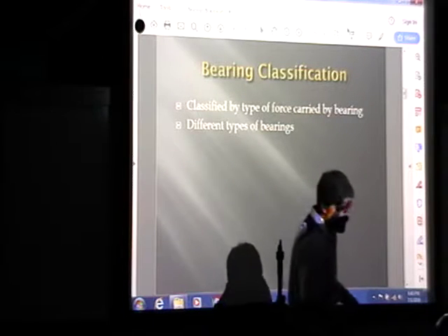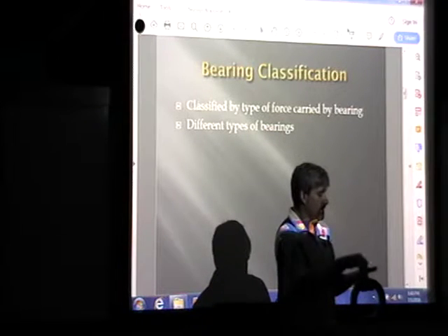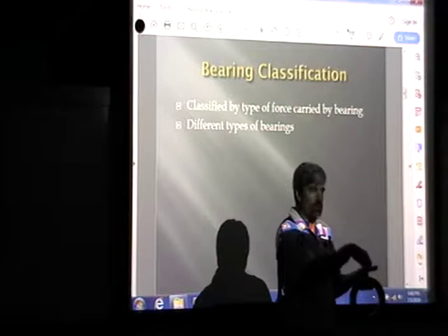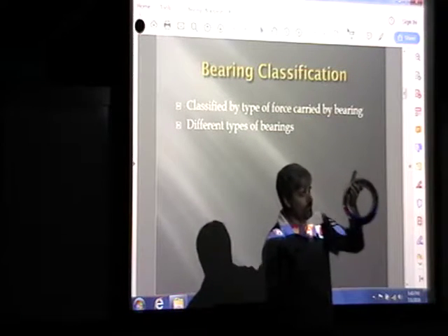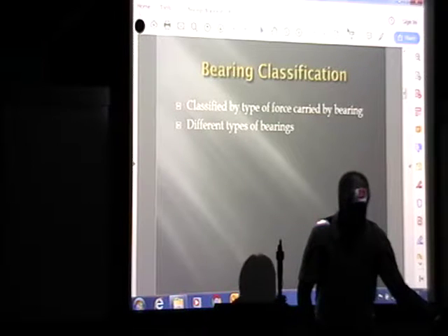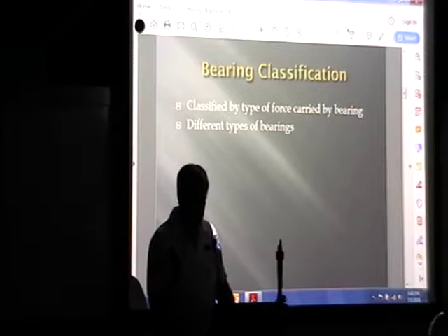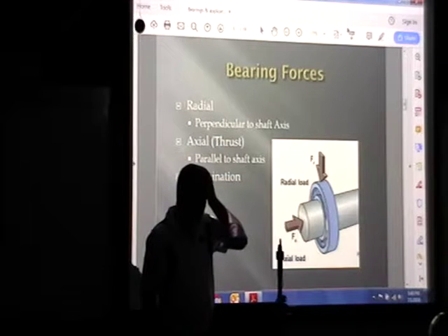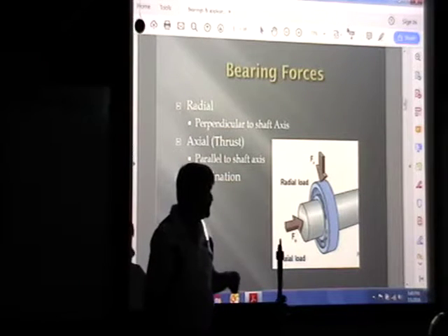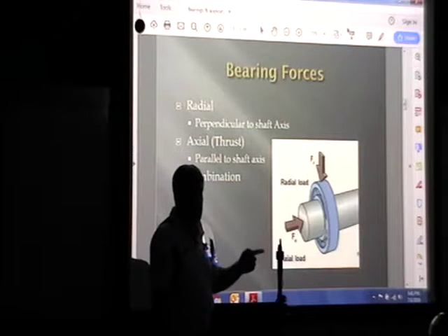And then just an example here of a radial bearing, where imagine this was on a shaft, your loading could take place radially on that shaft, and you can load it up that way. You see that in the camera? You guys can come up here and see these afterwards. And I've got another example here, but it's not very clear because it's all encased. So as I was talking about with these bearings, you've got a radial bearing, which takes the load perpendicular to the shaft, and then you've got thrust bearings, which can take axial load on the shaft.